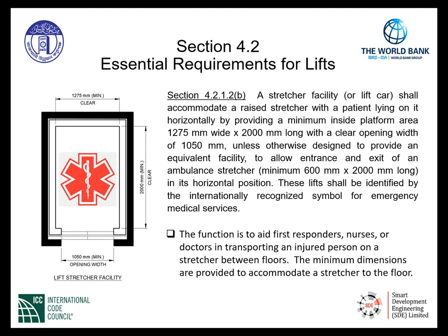Section 4.2.1.2, item B, gives us specific dimensions regarding stretcher facility. A stretcher facility or lift car shall accommodate a raised stretcher with the patient lying on it horizontally by providing a minimum inside platform area. Dimensions are indicated of 1,275 millimeters wide by 2,000 millimeters long, with a clear opening width of 1,050 millimeters, unless otherwise designed to provide an equivalent facility to allow entrance and exit of an ambulance stretcher.